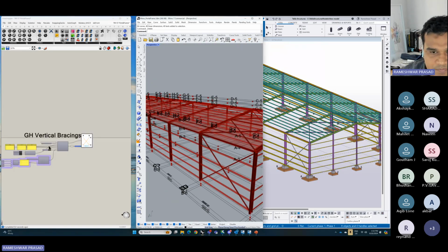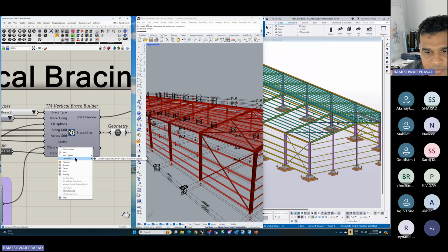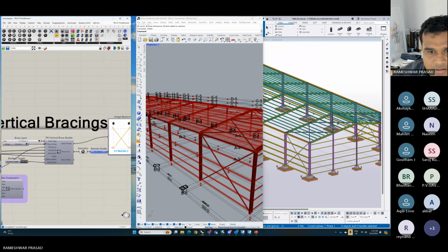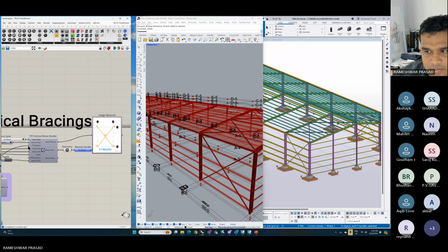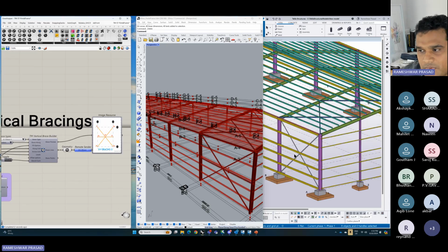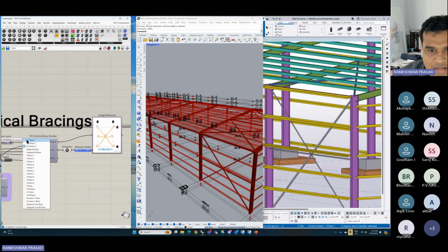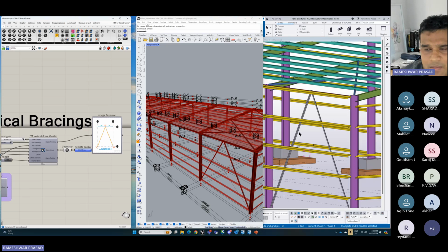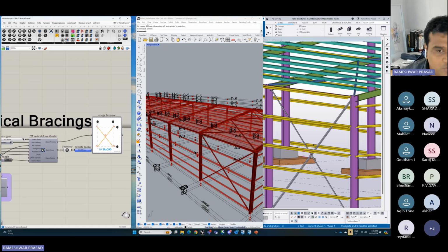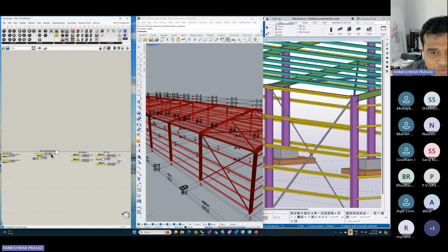See, if I want to change, let me just disconnect this and, did you see that? Over here, did you see that a new brace has been modeled? A tie has been modeled. We have configured somewhere around 18 to 20 types of braces, if I remember correctly, which will quickly scale up these types of bracings, and you can immediately change if a bracing pattern doesn't suit you. Okay, so XV brace 2. And similarly, we have done plan bracings as well.